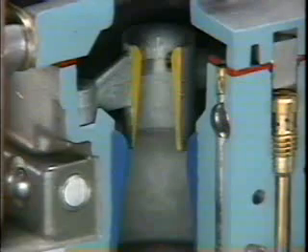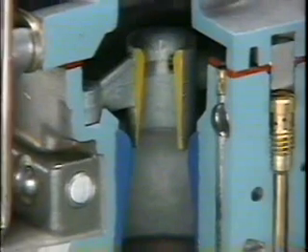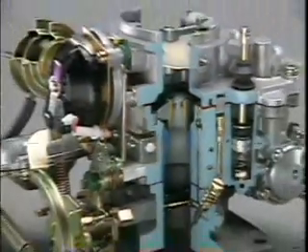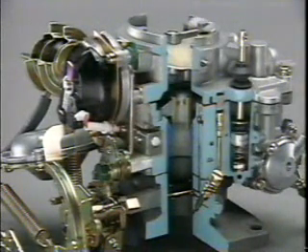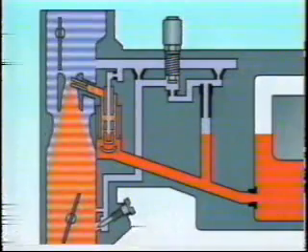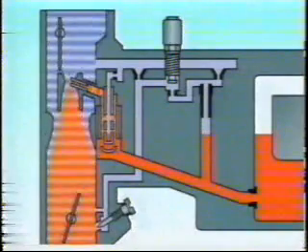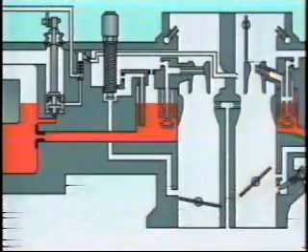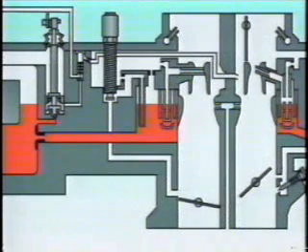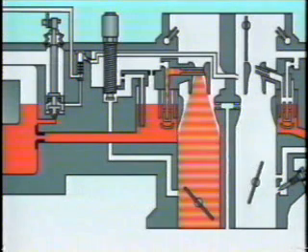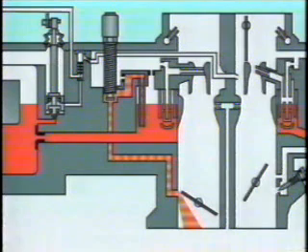This is how the air-fuel mixture is regulated during idling at low and medium speeds. However, this alone will not produce the power needed during high-speed operation. This is why the double-barrel carburetor has a secondary barrel. The construction of the secondary barrel is the same as that of the primary barrel. It has a high-speed circuit, which is its main circuit, and a low-speed circuit which prevents the mixture from becoming too lean when the throttle valve opening on the secondary side is small.